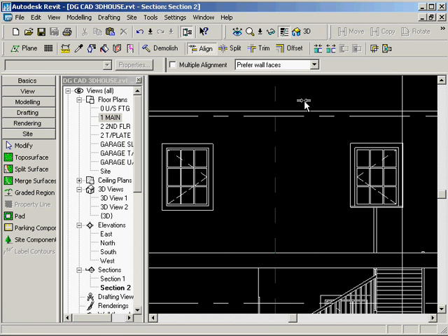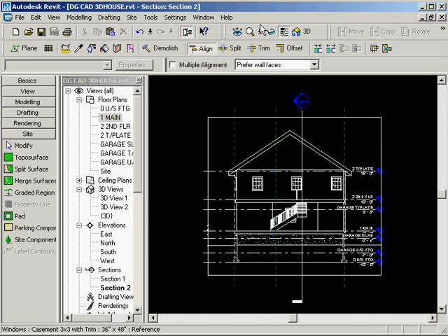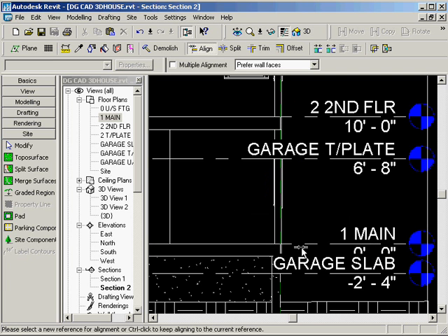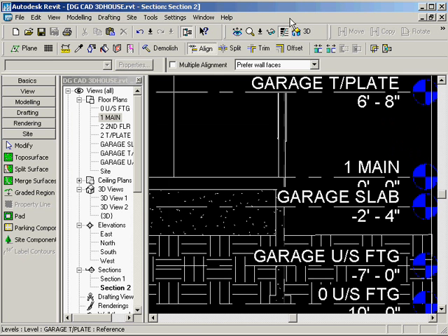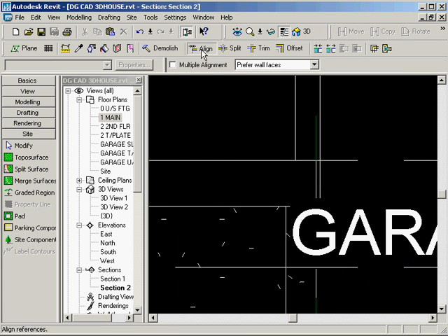I'm just going to do a ZE for zoom extents in here, and I'm sure you can see the power when you start getting into details and vertical alignments, when you can get in nice and close here, and you can use that alignment tool to grab an edge, for instance, somewhere along here, and align that with another edge and then lock it in.